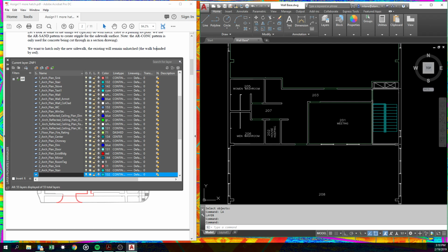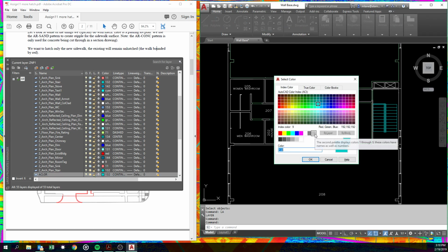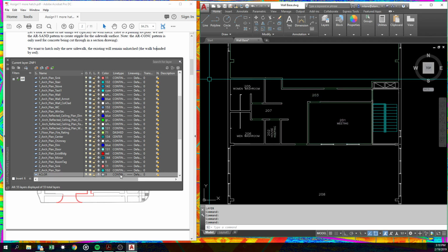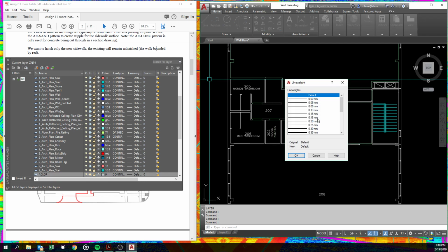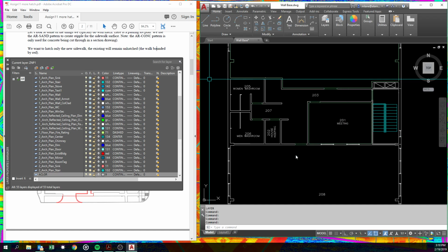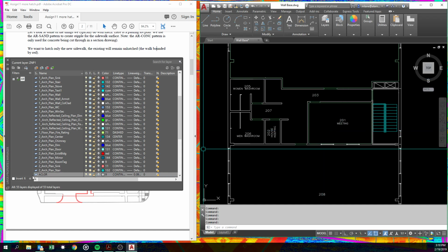Oops, let's put my caps on. A Ceiling Grid. We'll make it color 9. That's this one here. And I think it had the 30 in your handout for the AIA layers. That's really off. It should be 9. We're going to make that current.